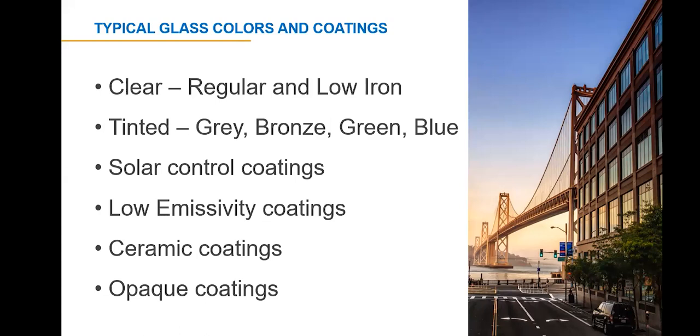Special coatings can be applied to the float glass to make it reflective to shortwave radiation, that's the IR that you feel from the sun, or to long-wave radiation, that's the heat that's inside of a building. These coatings go by a variety of terms. The two main types are pyrolytic coating, a metal oxide coating applied on line, so during the glass production, at high temperature. This coating is fused into the glass surface, making it extremely hard and durable. It could be called online or hard coating.